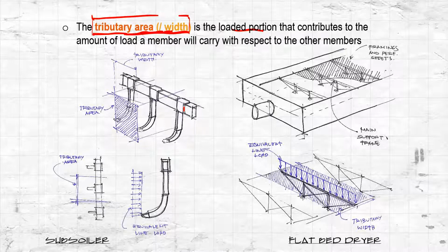In some types of soils that are really hard to break, this implement is used. By the way, when we say implement, it's being pulled by a tractor. So for example, this subsoiler is attached to this beam right here, and there's another subsoiler right here, and then another subsoiler, so they are spaced at some distance.